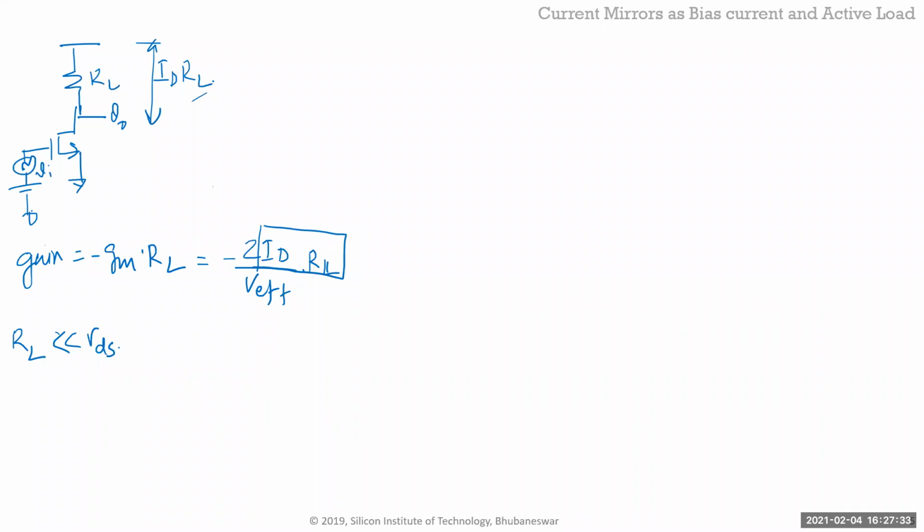Okay, let's take an example, right? Let's say the VDD was 2 volt. This is 1K, or 1K will be too little again. So let's say 100K, and so I want this output. Ideally, where do you want that DC output to sit? Because when I give a signal, it should go up and down. It's an AC signal, right? If I give a small signal sine wave from that point, this should do a large signal sine wave like this, right?